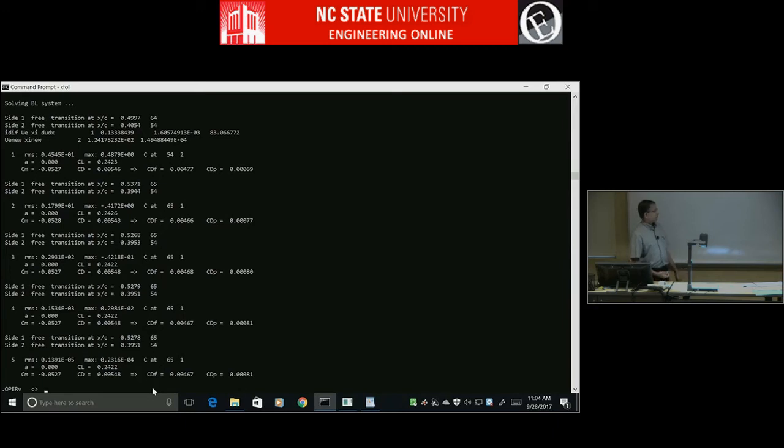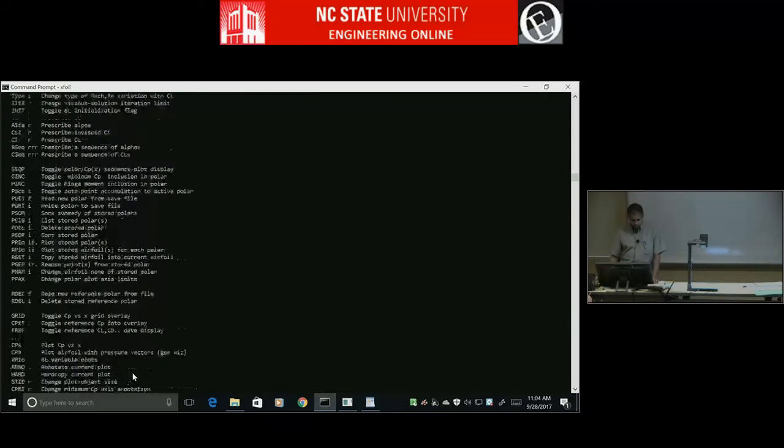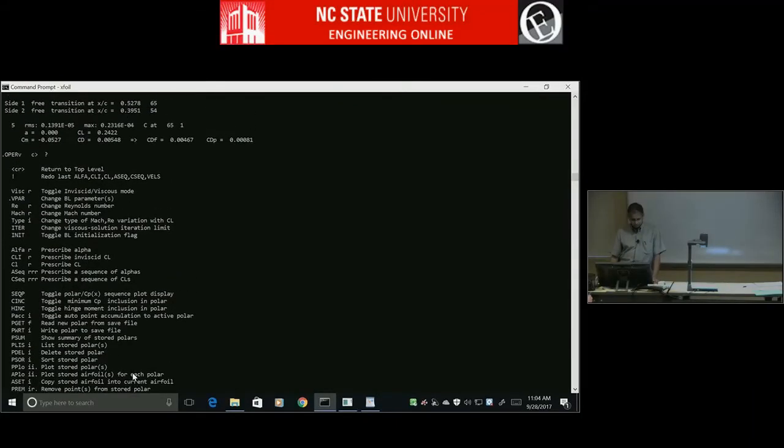So that's one more thing. By default, it will run 10 iterations, and you can change that, I believe, somewhere, iter. Yeah, this iter will change the number of iterations. So you can give it 100 or something if you want. Usually, if it doesn't converge in 100 iterations, it's not going to converge. It'll try 100 times, and it'll just give up and go on.